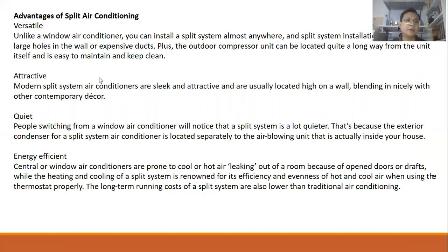Unlike a window air conditioner, you can install a split system almost anywhere, and split system installation doesn't require large holes in the wall or expensive ducts. Plus, the outdoor compressor unit can be located quite a long way from the unit itself, and it is easy to maintain and keep clean because we only need a motor blower to operate inside.